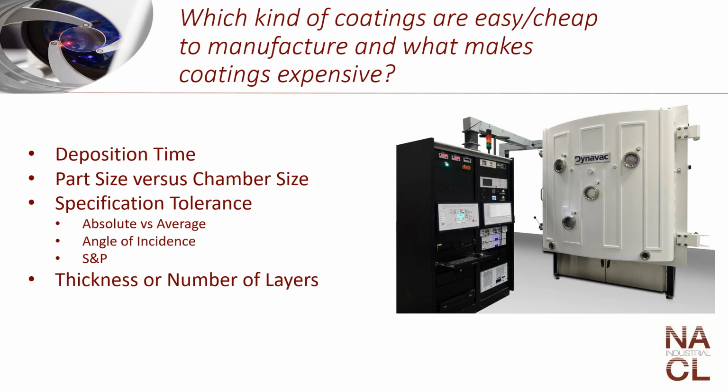So knowing the difference between absolute and average requirements is important. A lot of times we will see an absolute requirement where an average is more than fine. And other times, we'll send a spectral trace where we've quoted an average, and we have to do a level of education and let the people know, maybe even send tabular data to show them that yes, we're averaging that, but we at no point said that we would be below 0.5% across an entire operating wavelength.